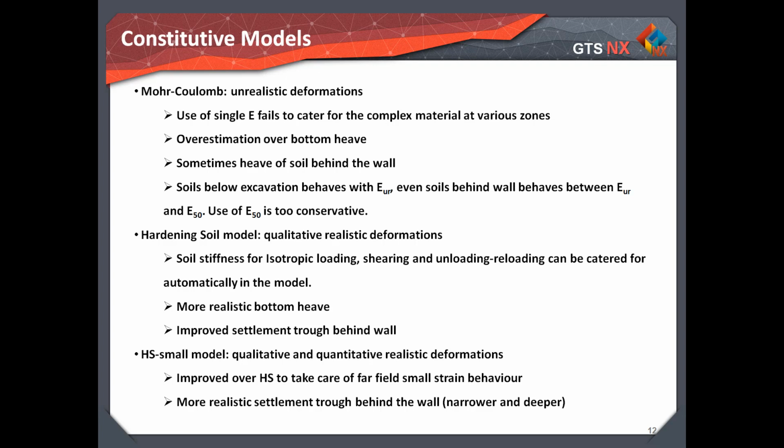Soils below the excavation behave with unloading stiffness. Even soils behind walls behave between unloading stiffness and the secant stiffness. Use of secant stiffness is too conservative.